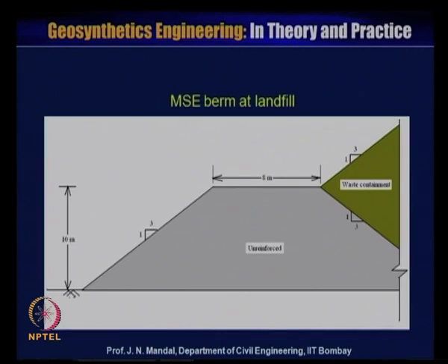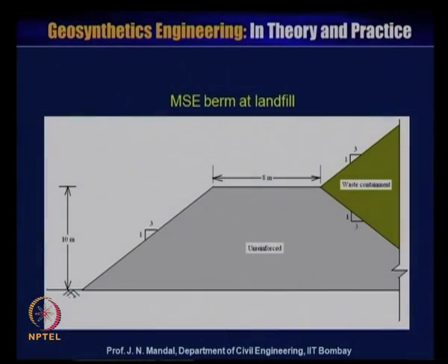Now we'll discuss this MSE berm at the landfill. So here is the landfill, the waste containment. It has a slope of 1 vertical to 3 horizontal, and this is 8 meter here, this 3 horizontal to 1 vertical, and height is about 10 meter, and this is all unreinforced, and this is 1 vertical to 3 horizontal.